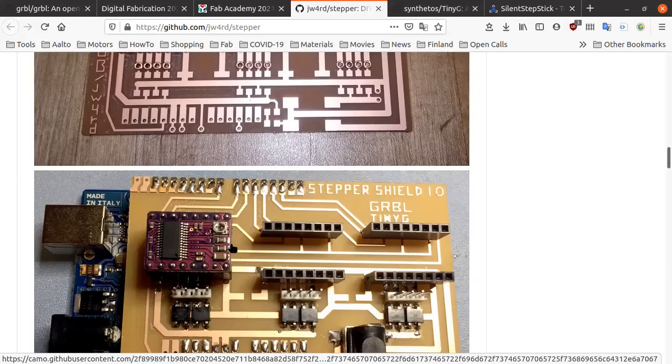So for the output week, you'll be encouraged to actually make one driver yourself. Make a board which includes either a ready stepper driver on it, or uses H bridges or plain MOSFETs. This simplifies it a lot and makes it less error prone. For this week it's perfect, because you have to do a little bit of customization or design yourself, and you should be able to put together a unique solution by using existing modules.